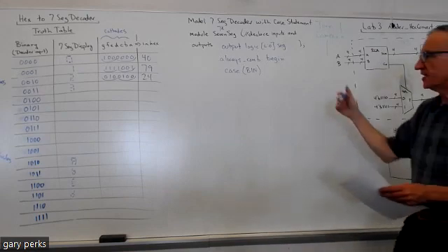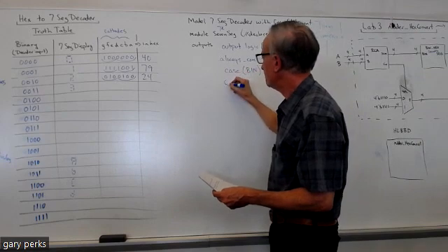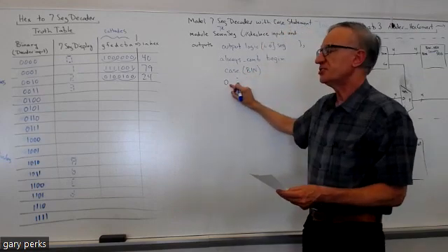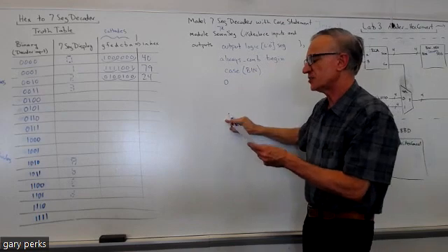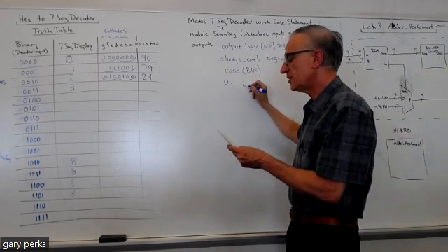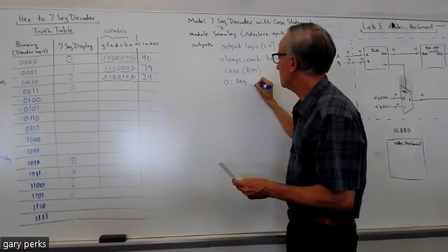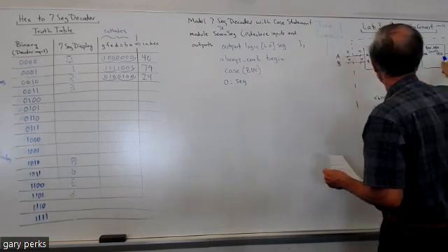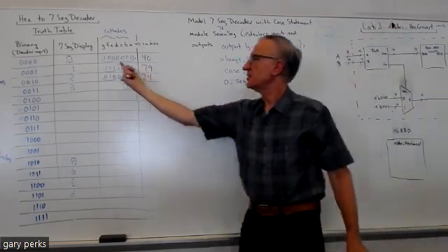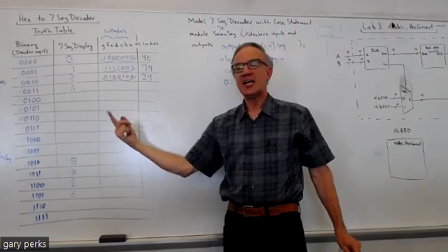Okay. All right. Then the next thing in the case statement comes the option. So you'll list your options just with base 10 numbers. So you put 0, then colon, and then this is where we use our truth table. Now we're going to assign the seg output the binary that we figured out for each of our hex characters.